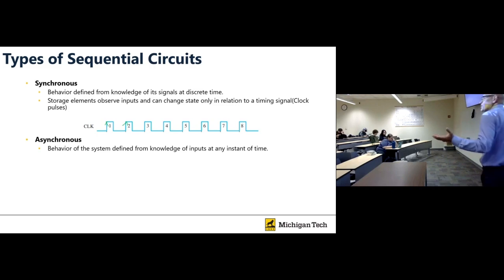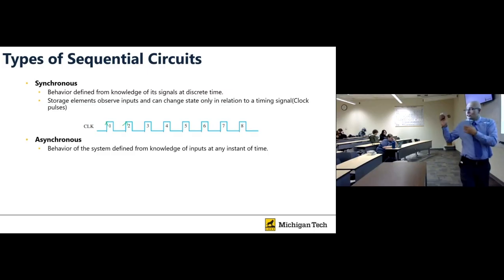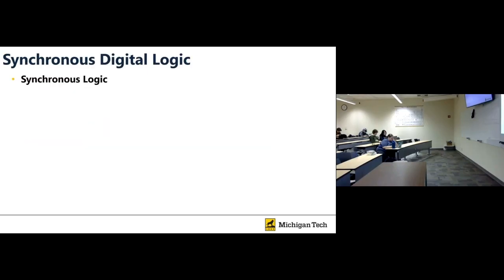Like before, like combinational logic, whatever we get as an input, we make a decision right away. We are not waiting to synchronize. We are not synchronizing with anything. So sometimes problems happen, but it's so fast. Why is it so fast? Because you just make a decision when the input comes. The only delay is the propagation delay between gates, and that's very, very low. So it's very fast, but the system is not that stable. We can see how we can fix it, but it still is very complicated.